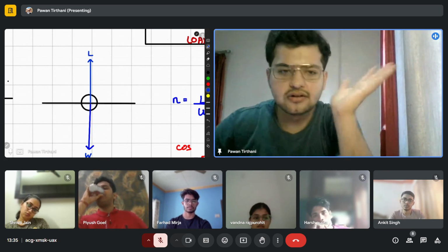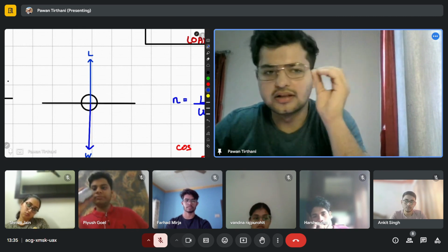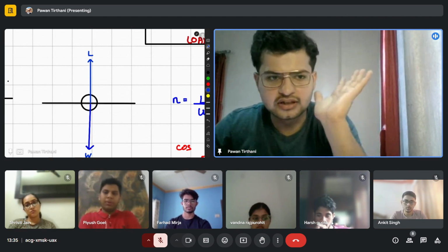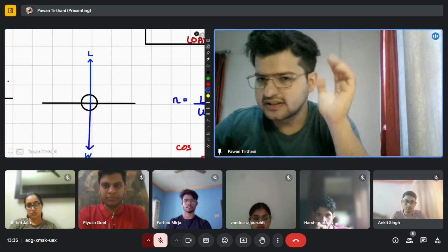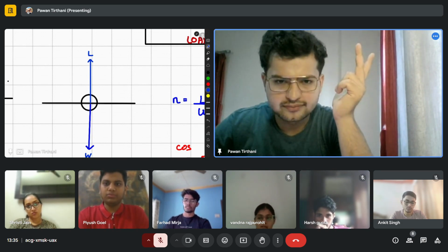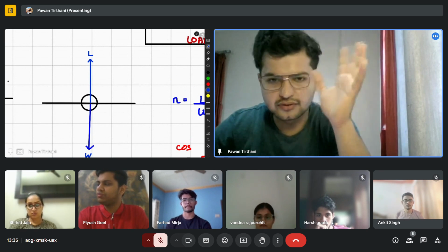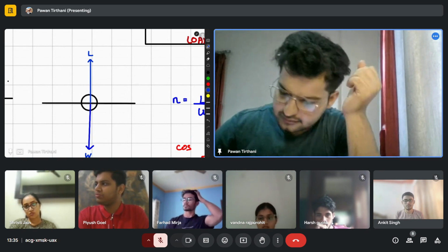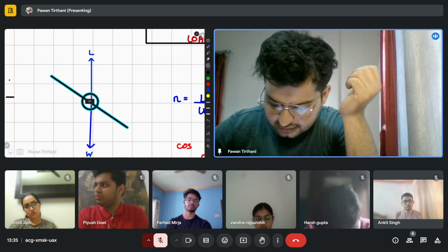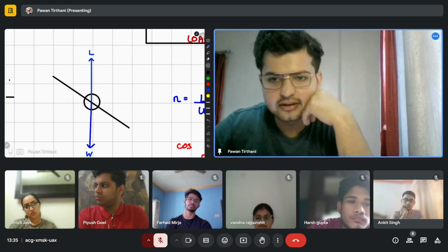To produce this much lift, you are flying at a certain angle of attack, at a certain speed, at a certain coefficient of lift. Can you change the surface area? No. You can change the speed and the angle of attack, or the speed and the coefficient of lift, right? Now let's say you have to get into a bank. I'll take a 30-degree bank. This is a 30-degree bank.